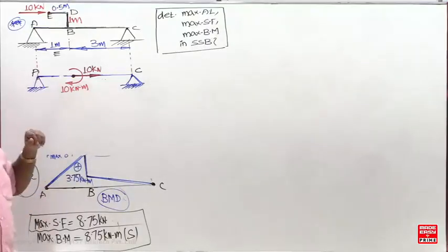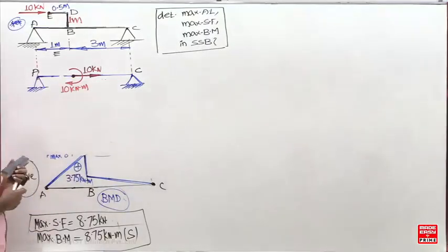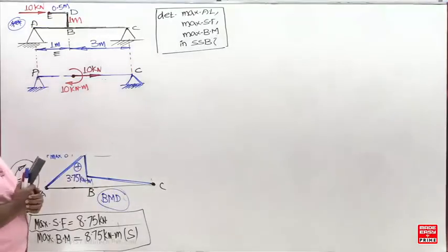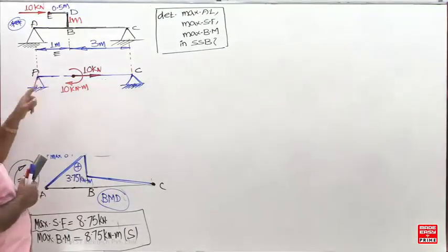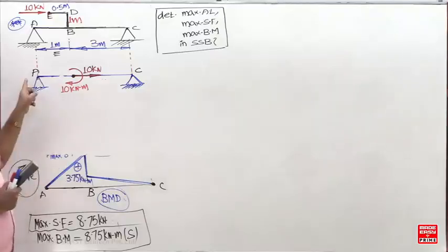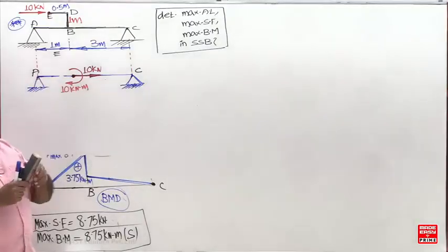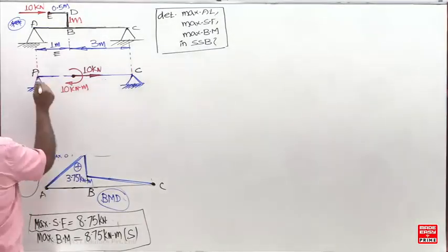Yesterday I explained this now. With the vertical hinge support, how many reactions now? 2: one vertical and one horizontal. Now how to keep the horizontal reaction? The net axial load is towards the right side, so the reaction should be towards the left side.